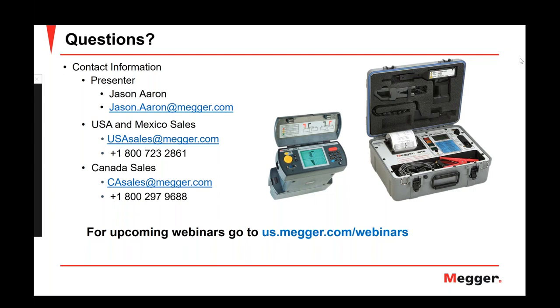All right, thank you. Additionally, Sanket, would I be able to run an impedance test with the BITE 2 on a 480 volt battery bank? Again, this comes down to the way the instruments function. With the BITE 2, you connect the current leads across the whole battery string, and then you take measurements across each cell. It's not the case with the BITE 3. On the BITE 3, you can test the same way irrespective of the voltage rating of the battery bank. But on the BITE 2, there is a voltage limit of 250 volts, so you cannot connect the current leads on a string greater than 250 volts.